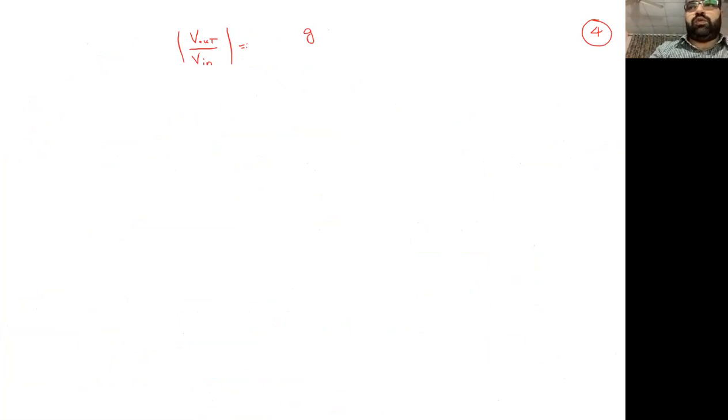Then we will discuss more about the phase too, because phase is very much important. So I'm just talking about the magnitude response, so I get rid of this sign. So we can directly write 1 over omega squared divided by omega P1 squared, and we can just plug in the omega P1 values as we calculated. I'm just not plugging it in, but you can plug it in.